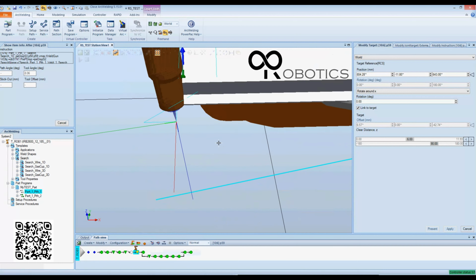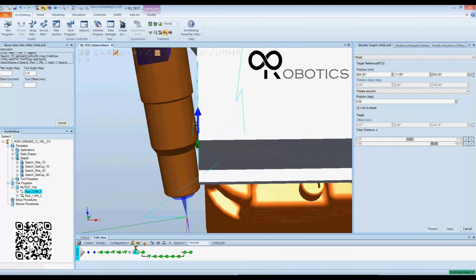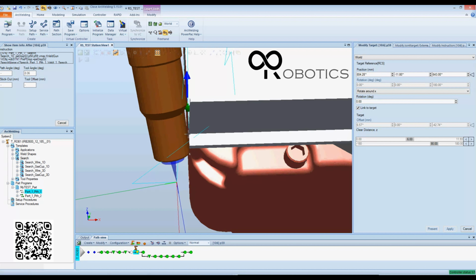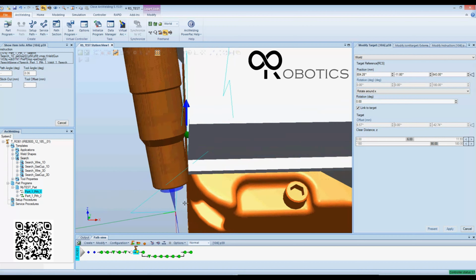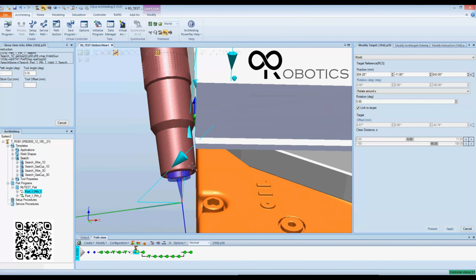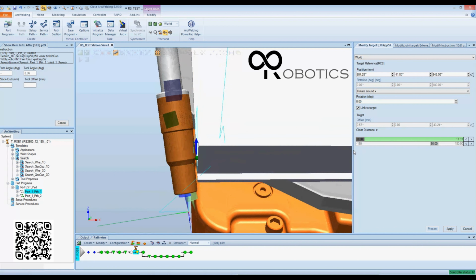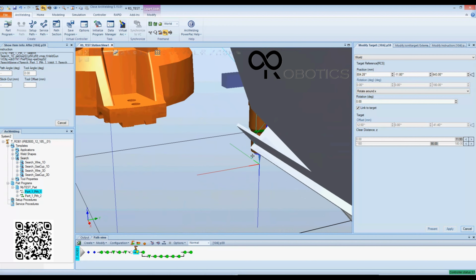And there, it's based off of the nozzle. What it's measuring here is from this z-axis, whatever that distance I told it that it needs to be, 5 millimeters I think it was, and it's going to measure from that TCP, or the wire, outside of that wire, 5 millimeters to that flush plane right there. And it doesn't mean that here won't touch, it just means that that's what it's looking for. So you can adjust this, how many millimeters you want it away. 0 millimeters, so it'll be touching at the same time. So you can set it up to be like that, so it's a straight up and down search right at that point.